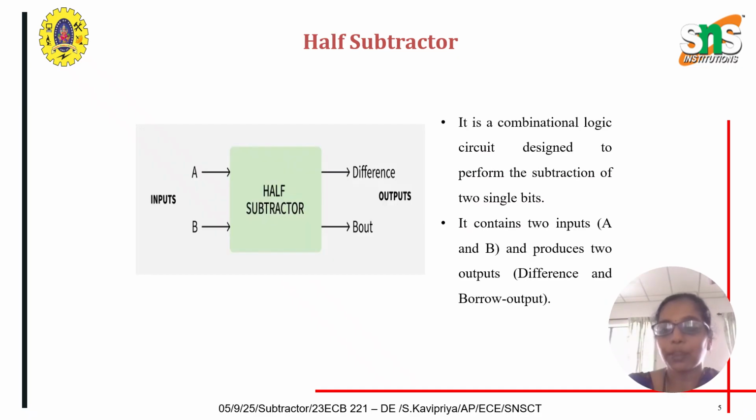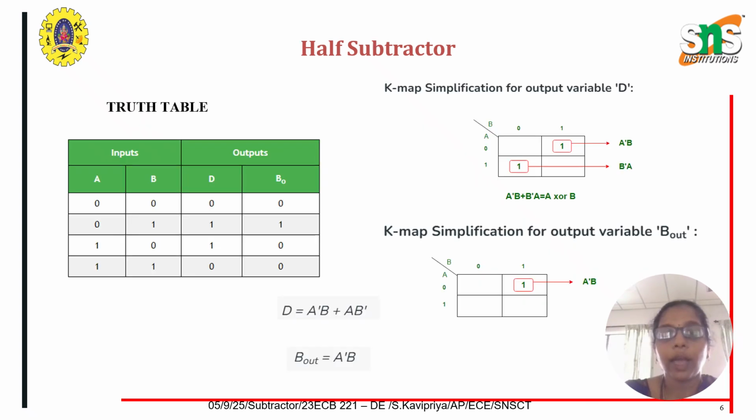So first, half subtractor, and this is a block diagram for half subtractor. It takes two inputs and it produces the outputs difference and borrow. And this is a truth table for the half subtractor. We have only two inputs. So totally we'll be having four combinations starting from 0, 0 to 1, 1. We have two outputs, difference and borrow, represented as D and B here. D will be 1 when input combinations are 0, 1 and 1, 0. And borrow will be 1 when input combination is 0, 1.